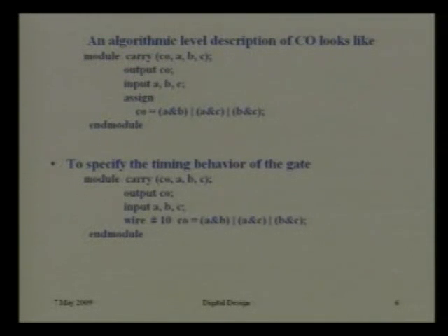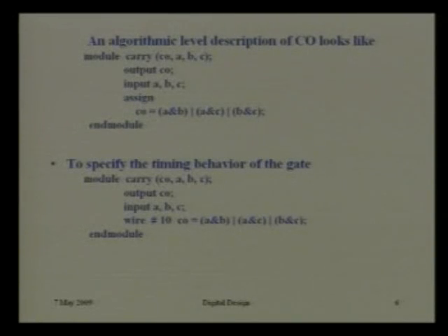For each module, one sum and one carry output. 1 plus 1 is sum 0, carry 1; 1 plus 0 is sum 1, carry 0. So, if I think that this is a module, then it has two outputs. The two expressions we have given.